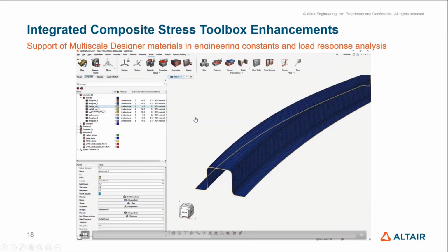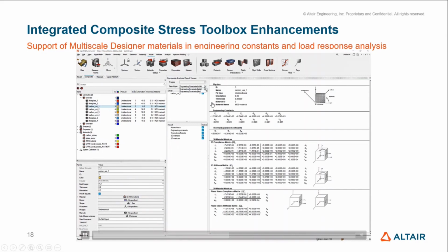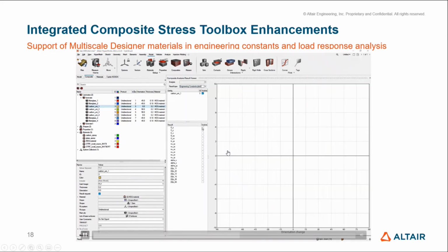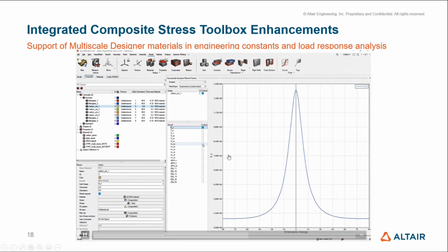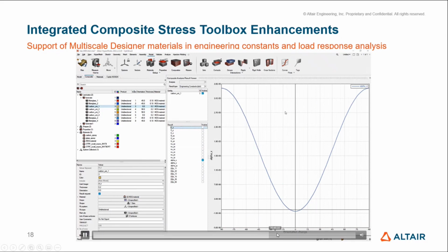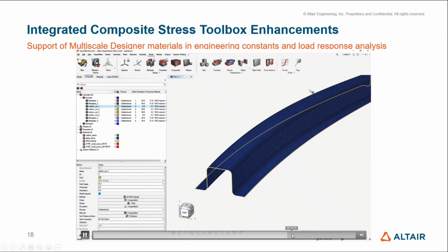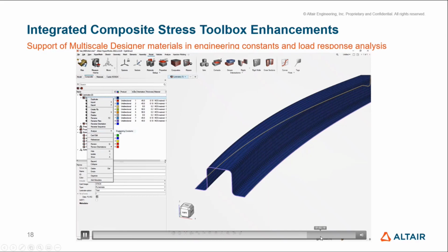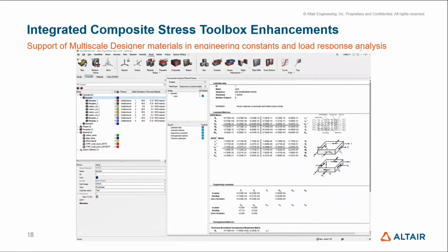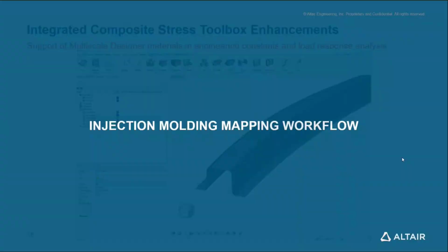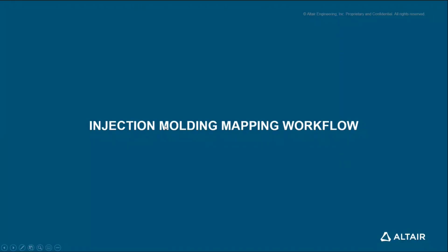except for the allowables. But now you can see here, I can do apply analysis. I'm going to get my applied values. I can go review, as with any other, all my values. I can do that same thing on the laminate, and it propagates through. And I can also do load response, just the first ply failure is then not available. And obviously the strength corresponding cannot be available as well.